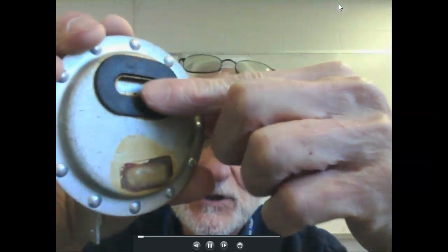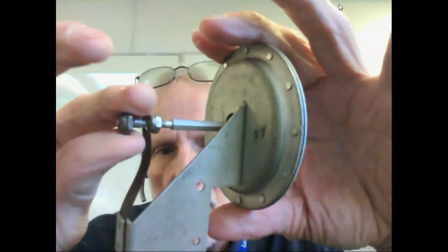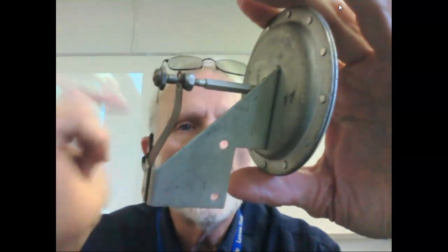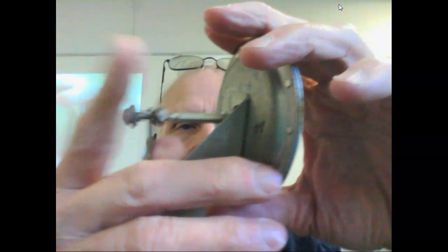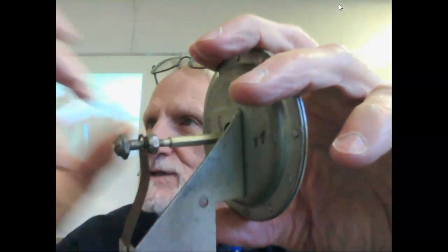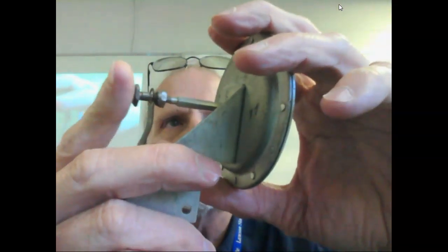Whatever we're going to measure the pressure of, we put it in here. It causes the diaphragm to push back. That comes over here and causes this right here to move. And then normally we use a limit. We combine it with another sensor that actually senses it. So a lot of our sensors are actually two sensors that give us one function.